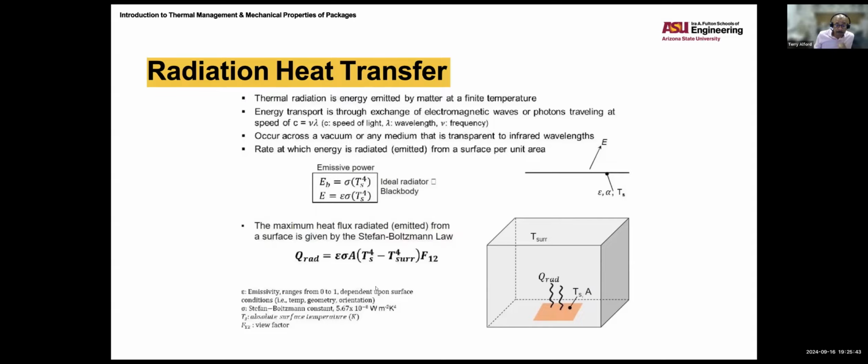And get the total. And here's my resistance, my ambient, so I can calculate the junction. It comes out to be 90 degrees C. So by flowing the liquid over the bottom side as an addition to the heat spreader, we gain 2 degrees C.